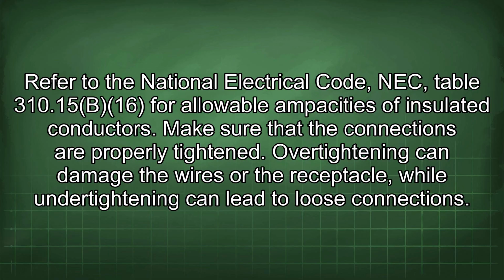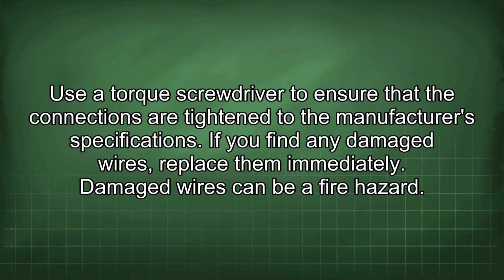Make sure that the connections are properly tightened. Over-tightening can damage the wires or the receptacle, while under-tightening can lead to loose connections. Use a torque screwdriver to ensure that the connections are tightened to the manufacturer's specifications. If you find any damaged wires, replace them immediately. Damaged wires can be a fire hazard.